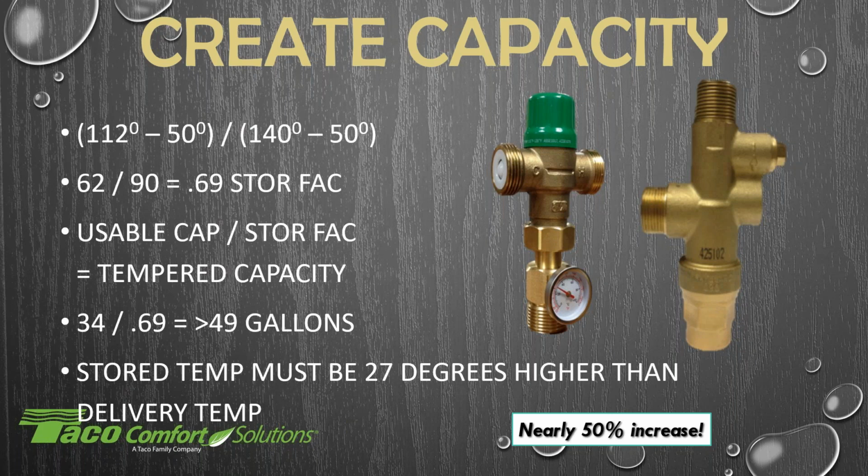And because this is sitting right on top of your tank, this valve actually comes as a kit. The kit includes a T to put onto the cold water side and a corrugated stainless hose, or corrugated tube, to tie into here, which would be your cold water supply. And then off the top is going to be your mixed water temperature feeding all your fixtures.